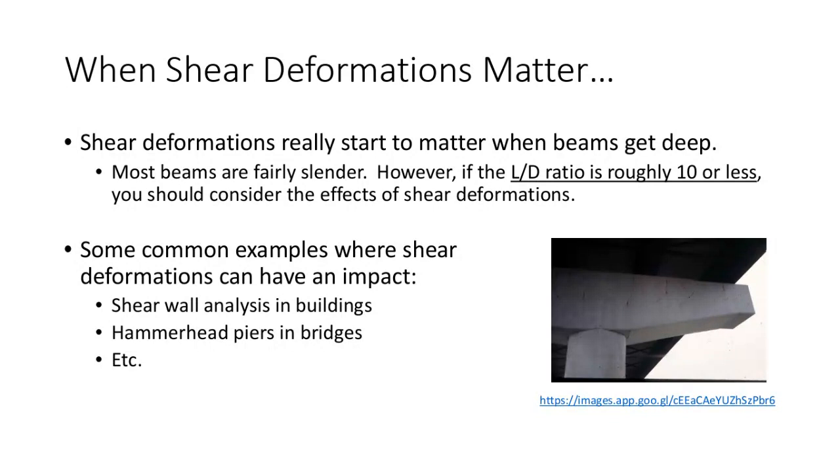And so some common examples where that might matter is if you're looking at a building and you have a shear wall in a building, that's really just a really super deep beam, like a cantilever beam sticking out of the ground. But another one, more near and dear to my heart in bridge engineering, is a pier. If you look at this component here of a pier and you idealize that as a cantilever beam, that is a really deep cantilever beam.